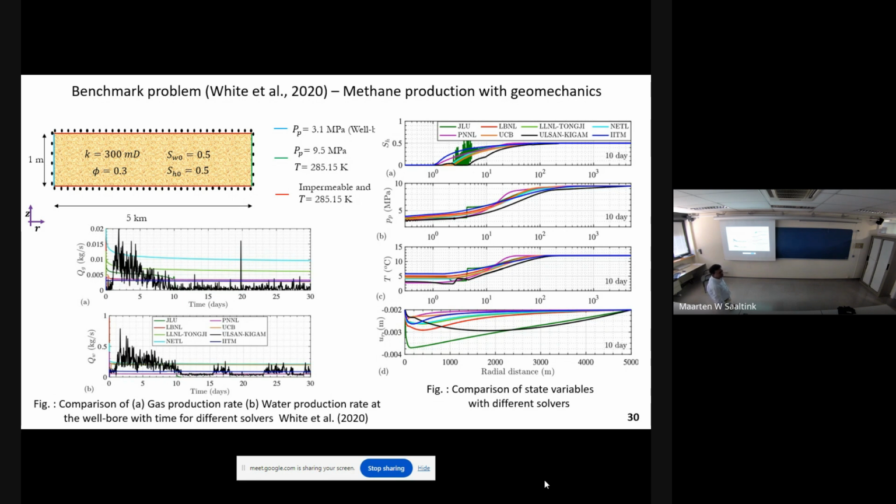Yeah, we'll discuss it maybe later. What is the right way of taking it? Because the pressure boundary condition is not correct. Stress boundary condition. I mean, unless you take a very long domain, the boundary condition effect will be significant. Is that radial? Radial. In radial you're right. But in the vertical direction, the boundary condition is critical. So I agree, in the radial it doesn't matter. But in the vertical, no, it does. That's right. Okay, we'll see.